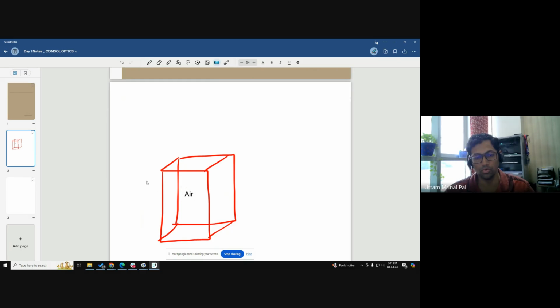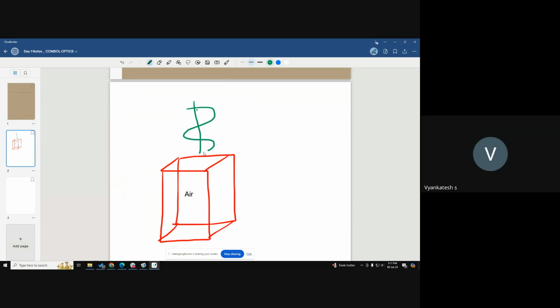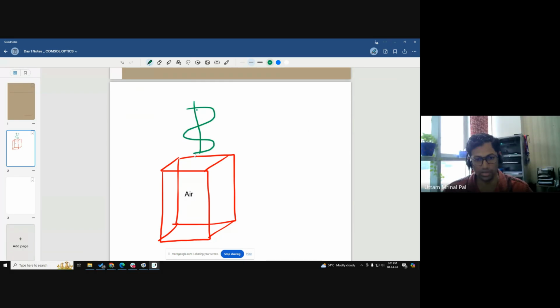Okay, so you can create an air box, a rectangular box of geometry, assign it as an air material, and then your objective is to propagate an electromagnetic plane wave. You start by normalizing the electromagnetic wave propagation in the normal direction, and then you can think about another angle of inclination. And so this is what we will be doing.